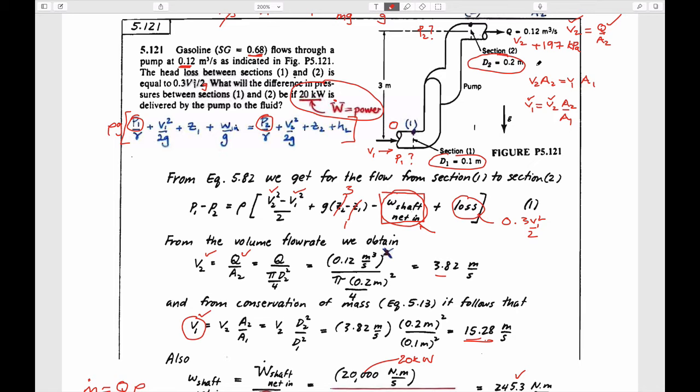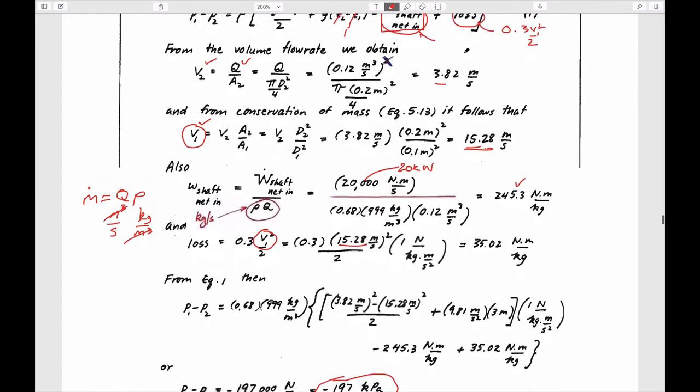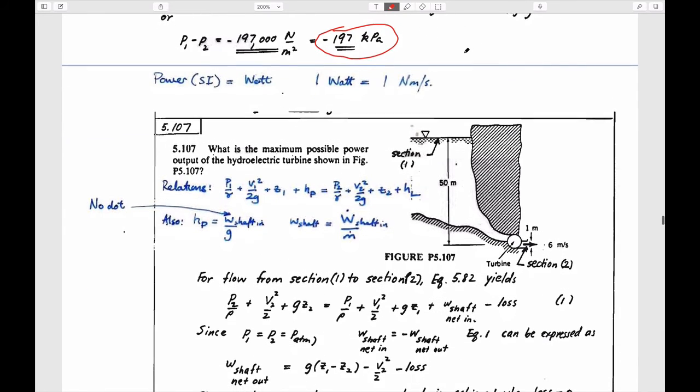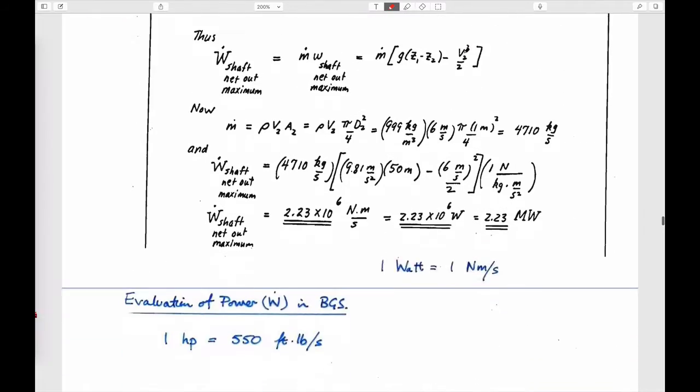Usually when things flow downstream, it goes from high pressure to low. In this particular case, because you're putting energy in at this point here, which is this pump head, the pressure that's downstream is increased because you're physically putting energy into the system. Okay, so it just becomes an issue of being able to plug and chug. I think this is the last one.